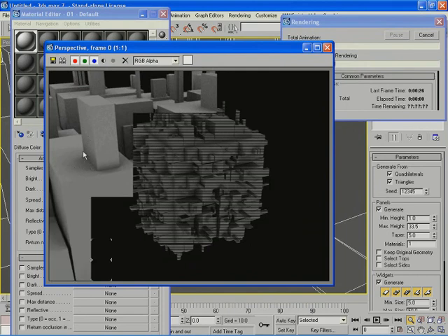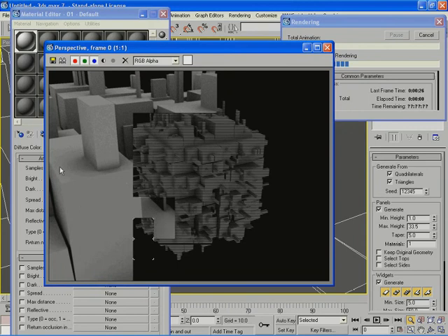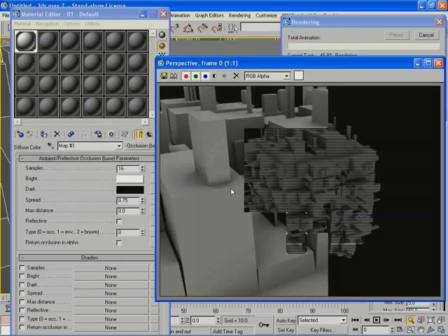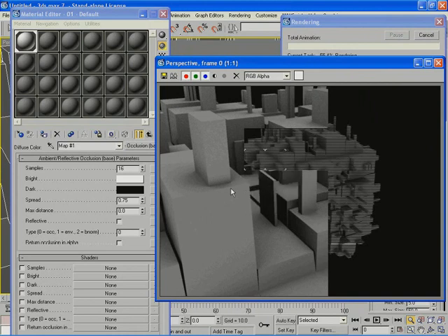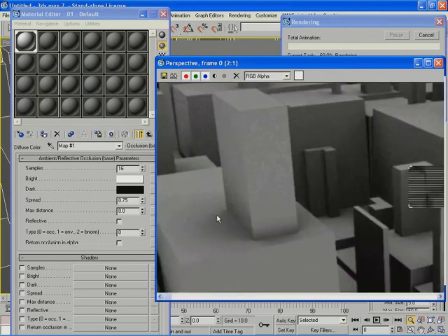And of course, with the ambient occlusion parameters that I have here, I can control the amount, first of all, of darkening. I can control the extent of the darkening, and I can control the resolution of the darkening, because if I zoom over here, I start to see some pixelation. And this is accounted for by the samples value down here. So the higher the samples, the better your rendering is going to become. So you're not going to get those grains that you get here, but you're going to get very soft and nice shadows.